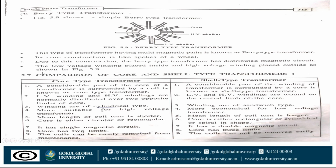Now we discuss the comparison of core type transformer and shell type transformer. In core type transformer, a considerable part of the core of a transformer is surrounded by a coil, and in shell type, a considerable part of the winding of the transformer is surrounded by a core. Second one is LV winding and HV winding are normally distributed over two opposite limbs of core. Means both the windings are on two different limbs, and in shell type transformer both the windings are wound on the central limb. Windings are of cylindrical type, and windings are of sandwich type.